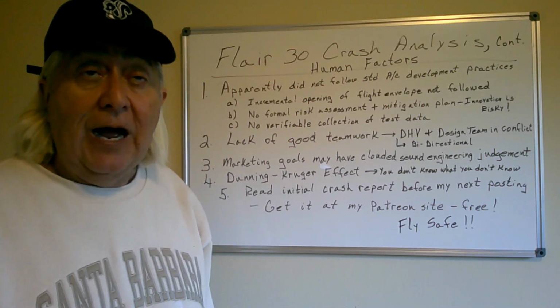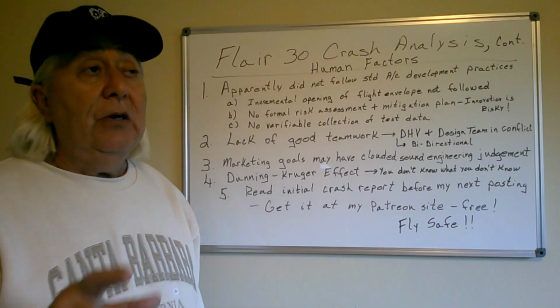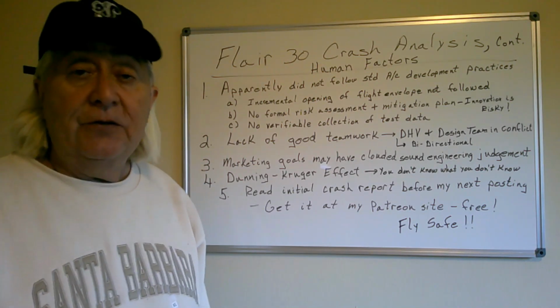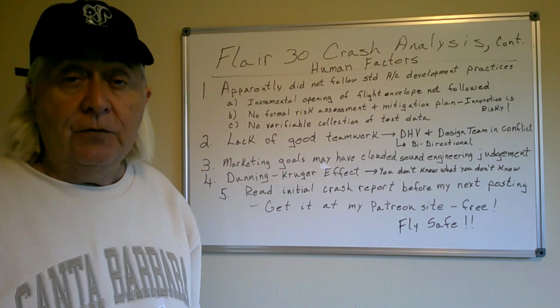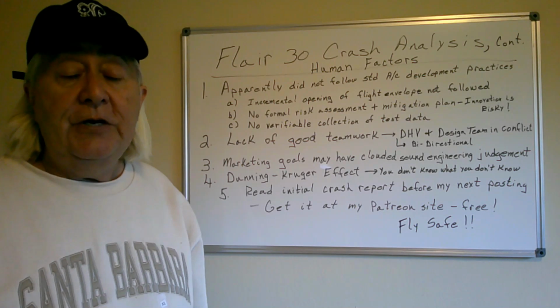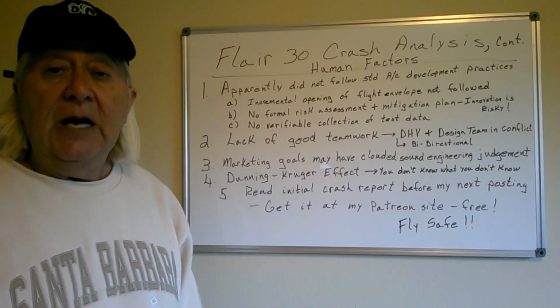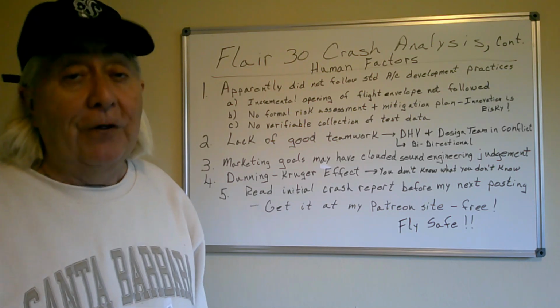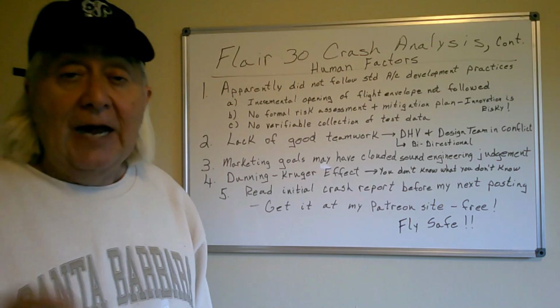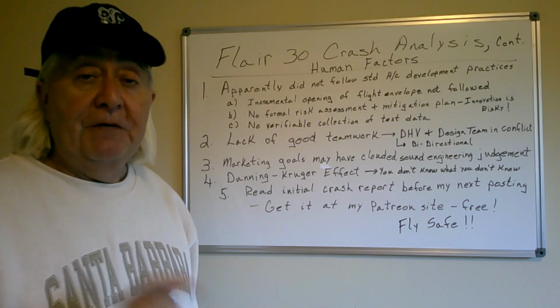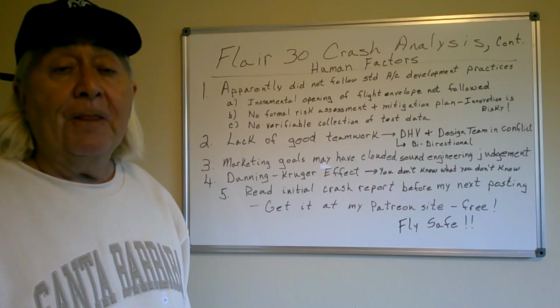That's how they could get... How do you get to 50 hours without crashing and then crash? Well, you haven't tested the full range of your flight envelope. You haven't tested the full speed range, the full bank range, all your different control settings. Because if they had, it would have fallen out of the sky sooner. Not on final approach, 50 hours into the game.